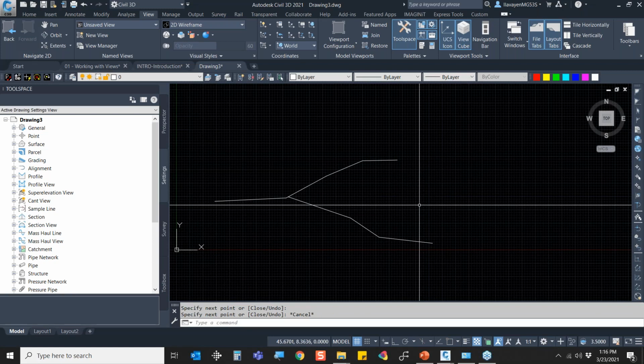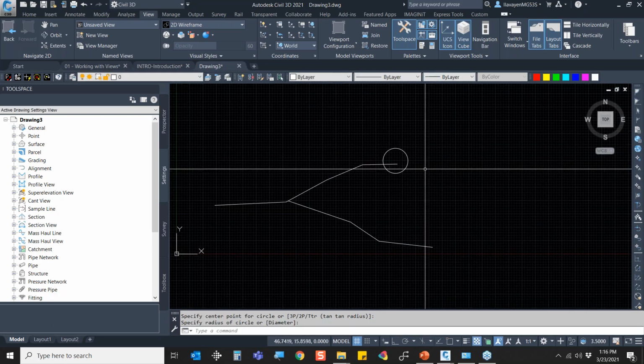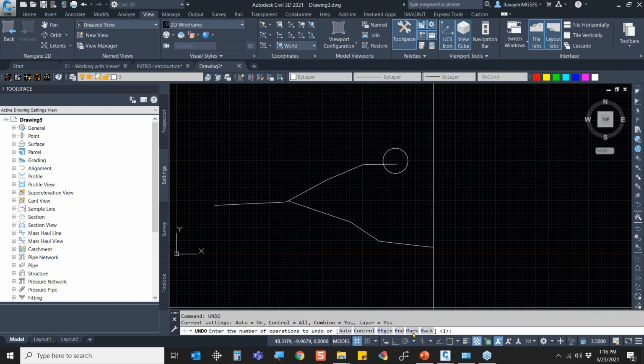And what I would like to talk about here is when you're working with option 1 and option 2, sometimes we end up doing a save as and doing a little bit of work. But what if it's enough I can do an undo? It's maybe just line work. So what I would like to show off here is the ability of marking my point in time and easily being able to roll back. That is, I'm going to hit the undo command. Typically, we just type U for undo, and I'm going to mark this location here.